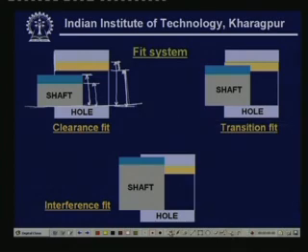Well, in this particular case, first of all, this is what we call a clearance fit. What is a clearance fit? Clearance fit means the shaft will be moving inside the hole in a loose sense, means there will be a clearance inside the hole. How is it being seen?